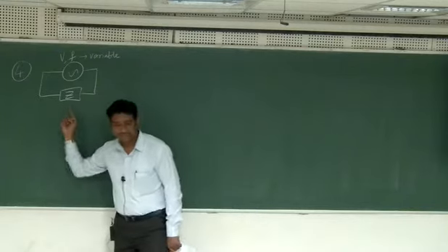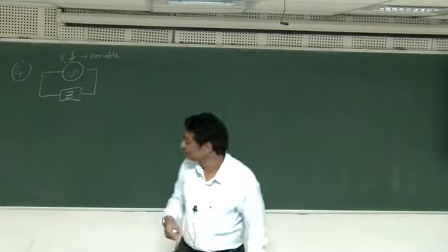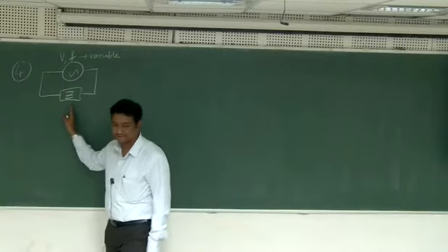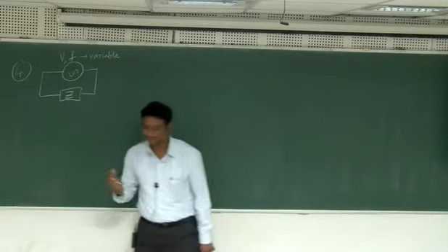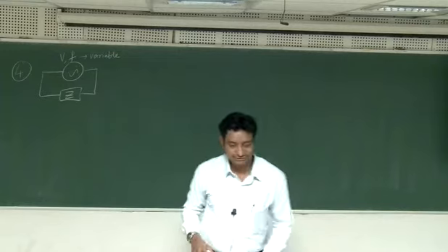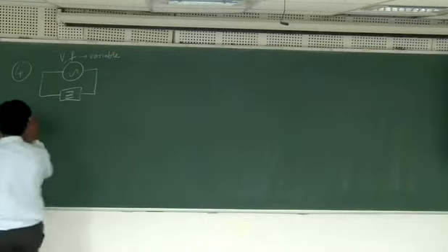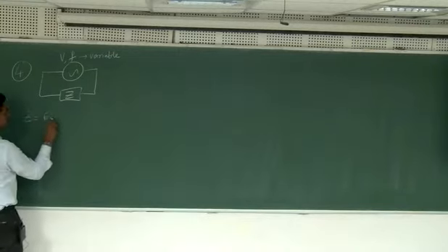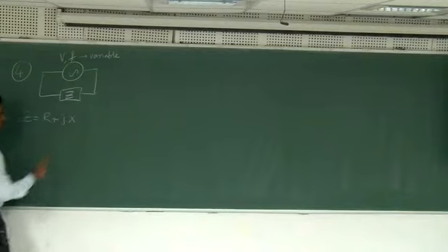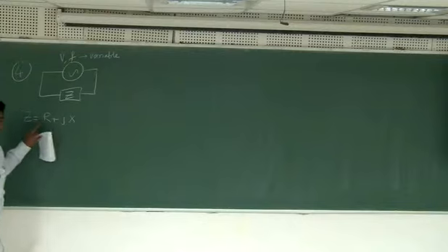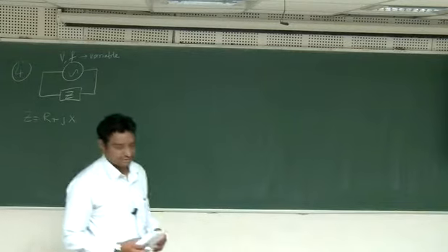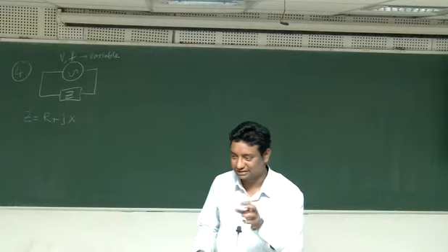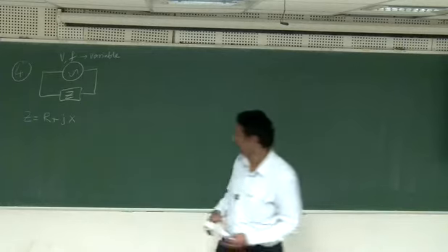So the first question I'd like to ask is, does the value of impedance depend on frequency, yes or no? Yes, it depends on frequency. Impedance is resistance plus j times reactance. The resistance does not depend much on the frequency. Strictly speaking, even resistance changes, but that's a different topic.